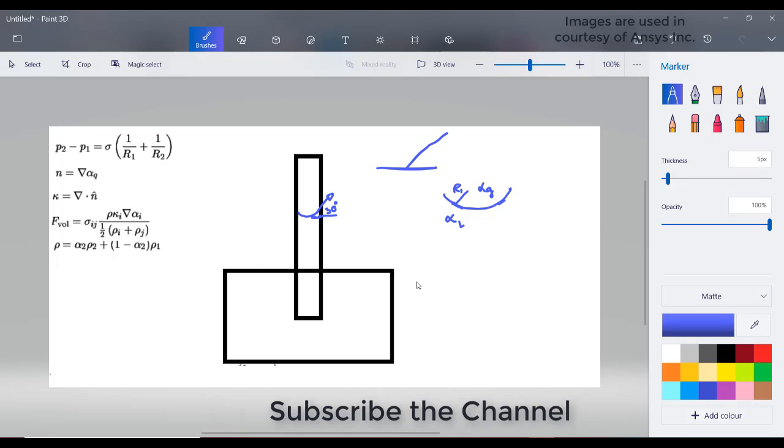This type of radius can occur when there is an extra amount of adhesion, an extra pull that pulls the water toward the wall. Initially it's a flat surface. Now if the wall tries to pull it, what happens? It tends to take a curved form. As it tends to the curved form, we now get R1 and R2. When R1 and R2 exist, there is a force term called the surface tension force.